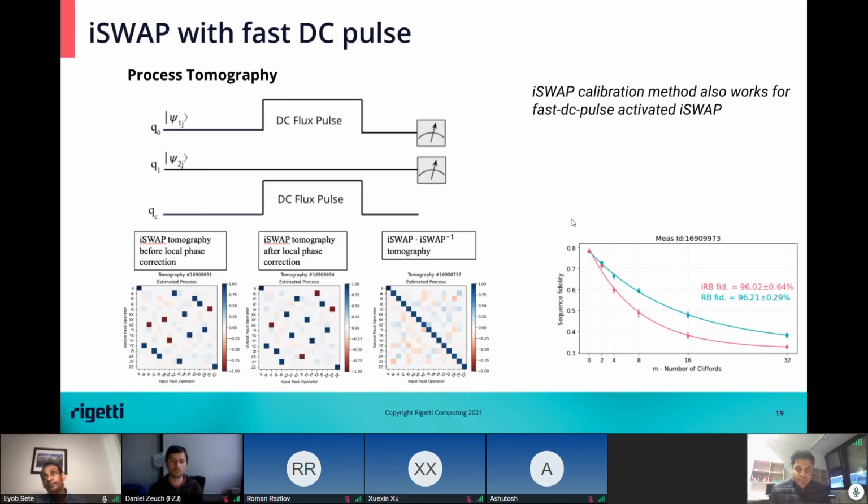You also mentioned scalability. Have you already faced challenges when implementing this on a 20 or 30 qubit chip? Good question. One of the things that comes with this kind of architecture is that almost all qubits are tunable, so you're sending flux signals to all qubits. So there is substantial crosstalk. For this edge, I park it at G equals 0. So you have to send some flux pulse on the coupler to park where G equals 0 is. Now, when you operate the other gate, because of crosstalk, that point could move. So we have to apply some compensating pulse on this tunable coupler to cancel